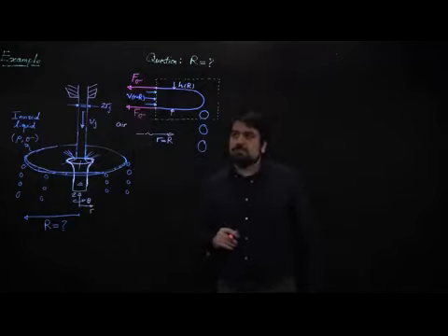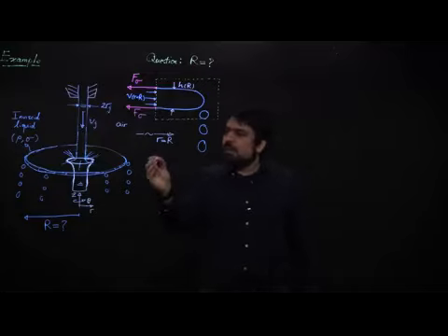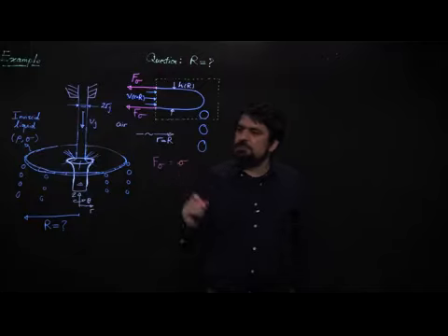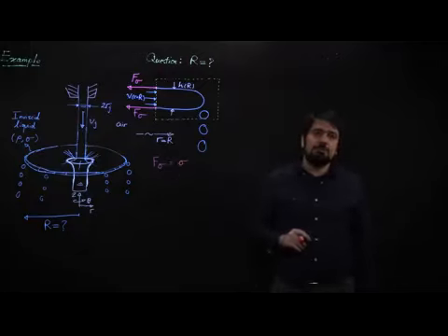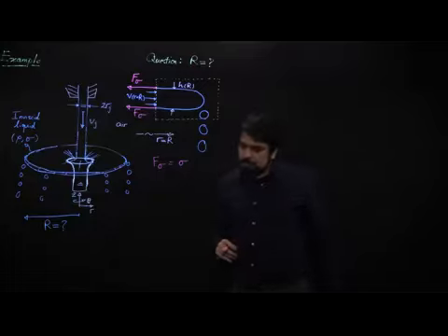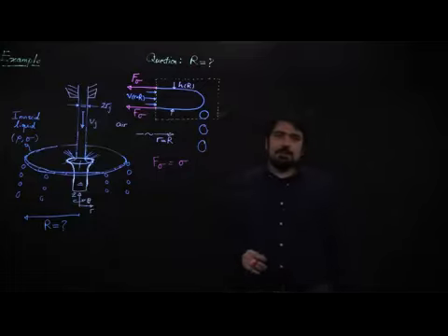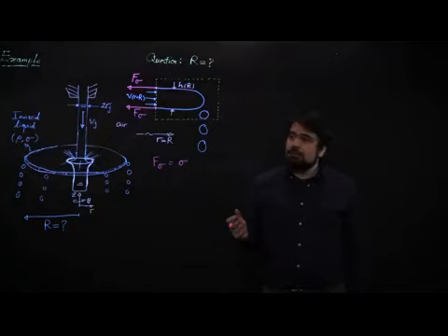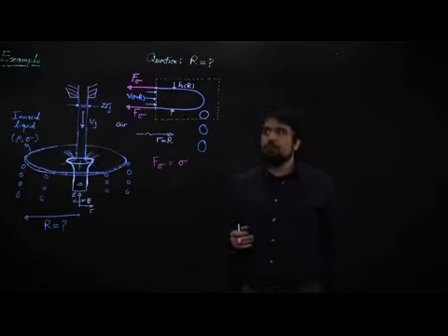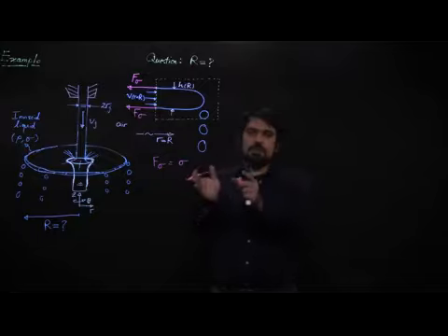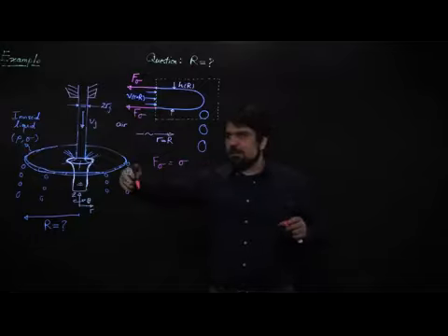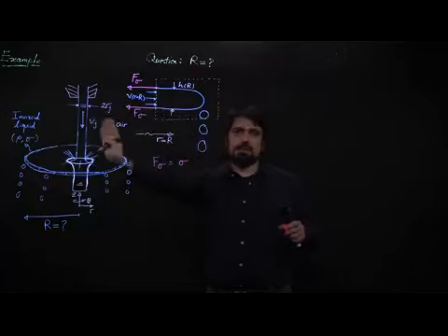This surface tension force is nothing other than the constant of capillarity, which is the surface tension between water and air, which is 72 times 10 to the power of minus 3 Newton per meter. And since it's a force per unit line, to get a force out of it, I need to multiply by a unit of length. The control volume that I've chosen is going into the board. It's basically rotating. This is the cross section of it, rotating into the board.